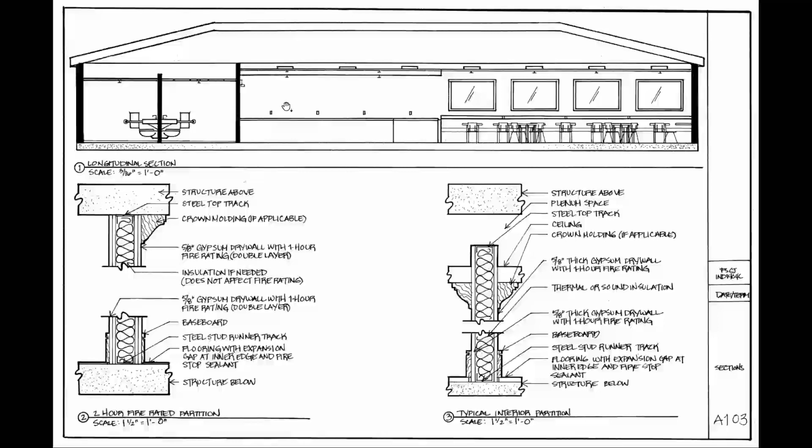Now right here on a section you can't see depth, so it looks like the sprinkler is attached right on top of or just below this fluorescent light, but it's not. One's actually a little bit closer to the back wall than the other, but we don't see depth in a section like this. We're just looking at this for the relationship of heights. But in any case, we've got sprinklers attached to this acoustical tile ceiling.